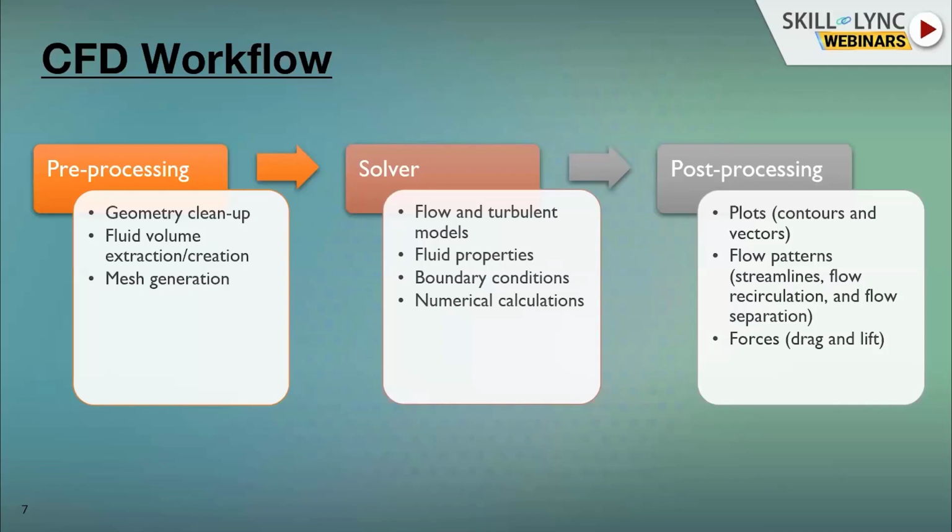He has to generate surface mesh. He has to generate volume mesh. Then the quality has to be cleared for both surface mesh and volume mesh based on the type of the mesh. After that, the solver settings part will come. In that, he has to select the right flow models, whether it is laminar or turbulent, and define the fluid properties, then numerical methods, boundary conditions, convergence criteria, the parameters which he needs to monitor for the convergence, etc. And obviously running the solution.